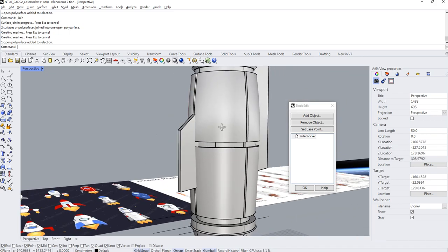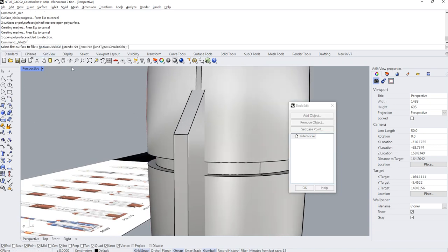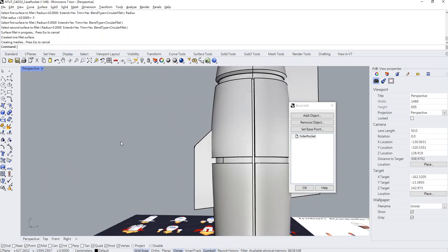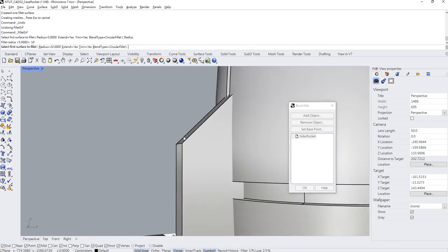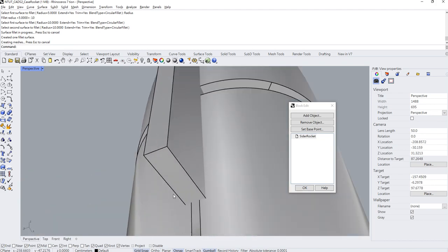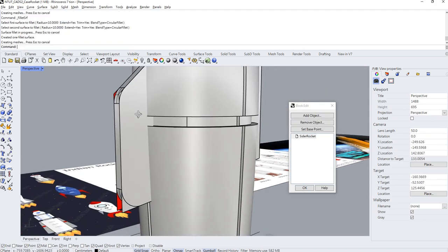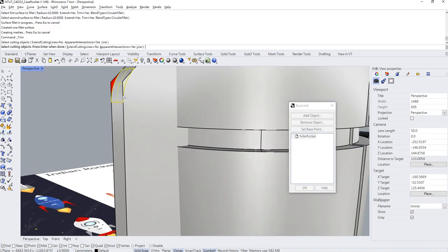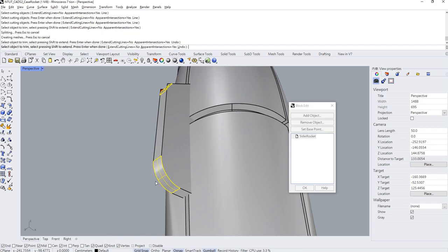So for this part, I hope we can make a chamfer corner. So let's choose fillet. That's radius 10. I think it's too much. Let's type in 5. Probably 10 will be okay. So let's use 10 again. Make this one become a 10 corner, and for this part as well. Alright, looks good. So again, we have to use trim, choosing the surface as the knife, press enter, and then delete the rest of the part.